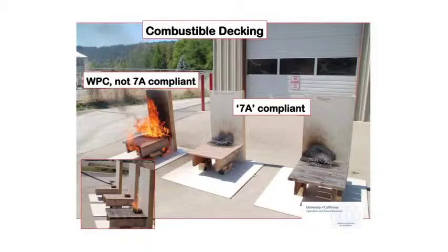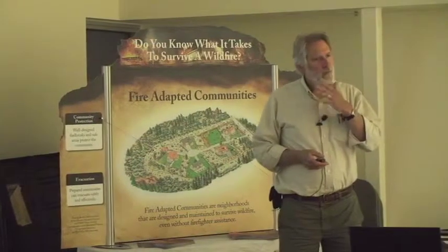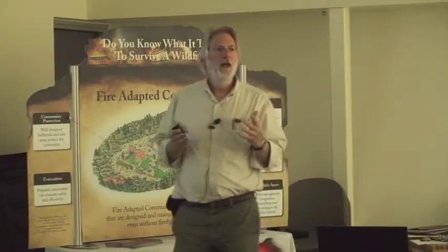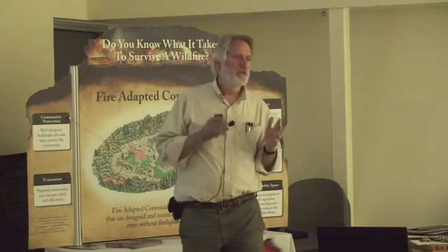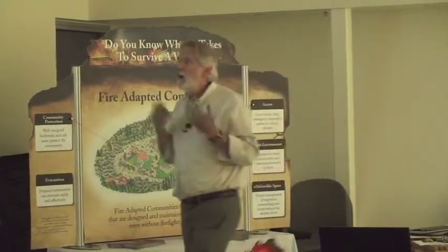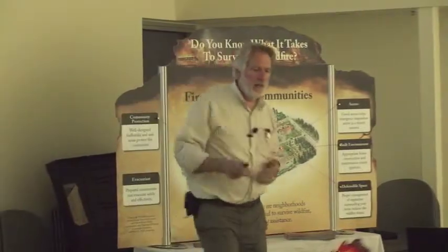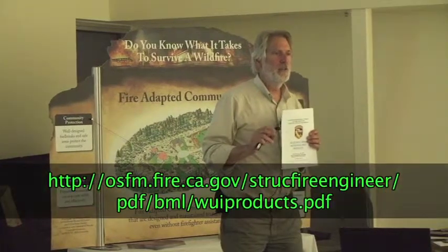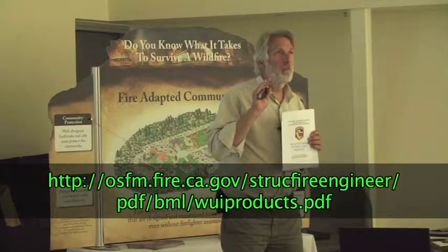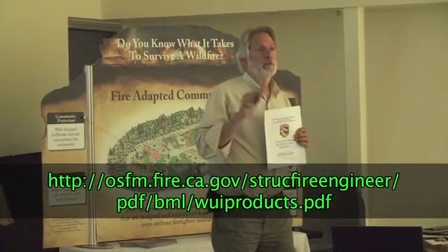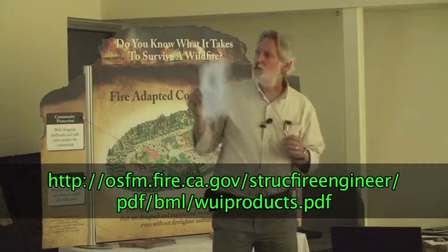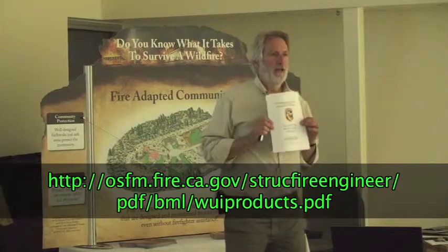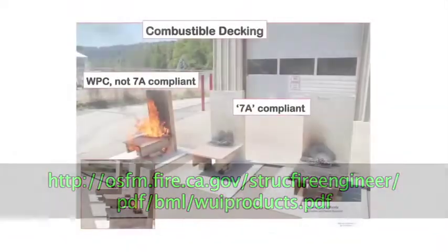So here, we can say that all combustible decking products are not equal. You have a way to differentiate to some degree how combustible a particular combustible decking product is. And one way is to just look at what's in this WUI product handbook, because it does provide some discrimination against, in particular, the products that are very flammable or very combustible versus those that aren't. And the way you do this is that this has a minimum heat release rate requirement to be approved for use. And this is an example of that.